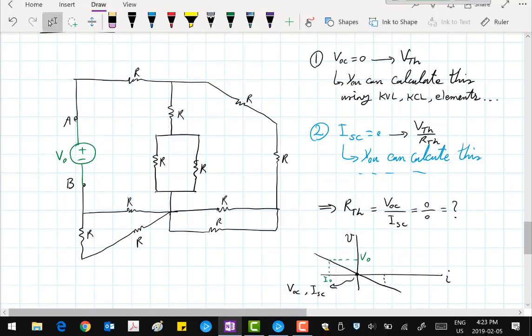Well, let's see. We are looking at finding the Thévenin equivalent of this big circuit, which means let's imagine we put it in a box. Now, my box is going to look a little strange, maybe. Okay. Now I have chosen to define my IV characteristics like this, and this voltage source, this V naught that I've put there, I have already indicated its polarity, right?